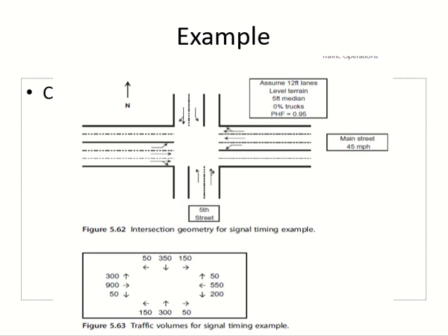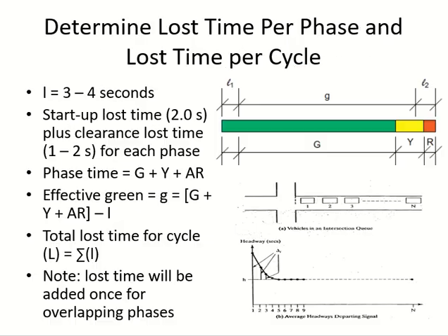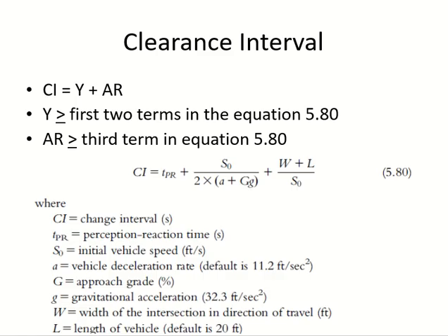So each direction will have its own all red time and yellow time. Not yellow. I think yellow is the same. There is no change in yellow. Yellow only changes according to speed. So if both roads have different speed, then the yellow time will be different. Otherwise, for both roads, the yellow time will be the same.